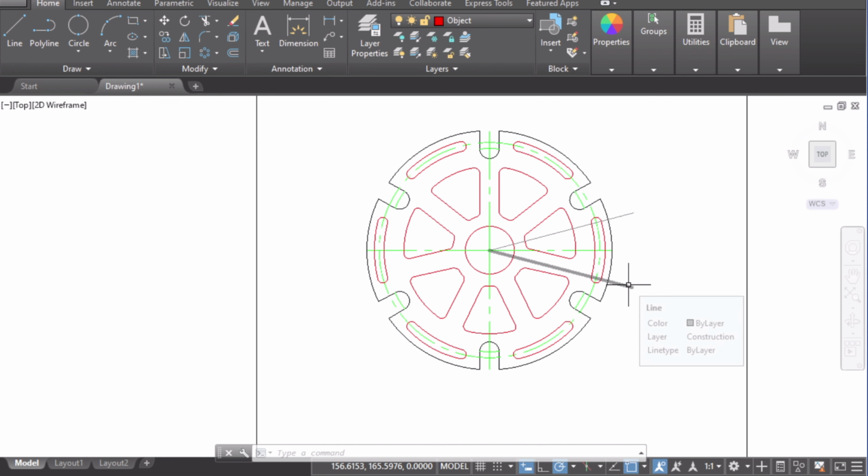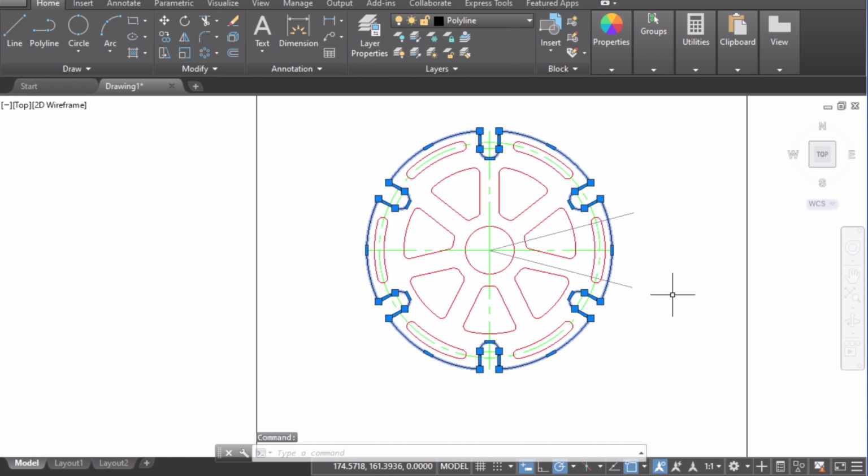The catch of this activity is how you can use arrays in a proper way to construct any complicated sketches, and at last how you can make polyline to combine, to stitch lines and curves together. That's it.